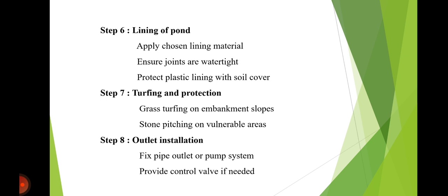So what are all the maintenance after construction? How can we maintain it? Here are simple notes for maintenance after the construction. Remove the deposited silt periodically. Repair the cracks, erosion and damaged lining. Maintain vegetation cover on the embankment. Keep inlet and spillway structures free from obstruction.